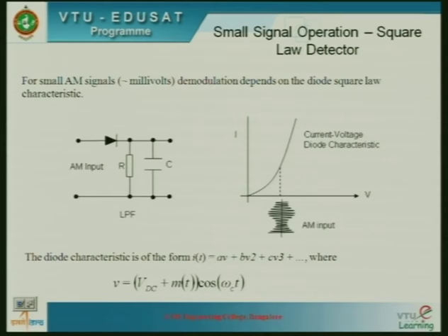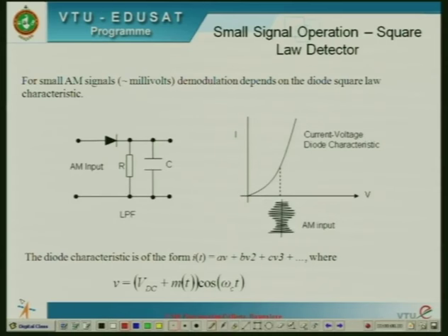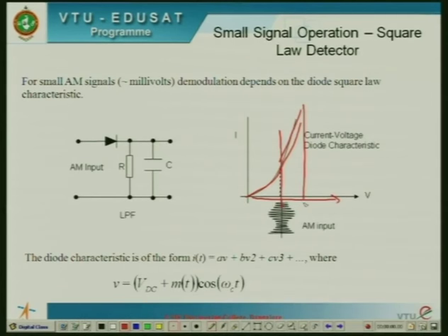So if we increase the voltage across the diode slowly, as we keep increasing the voltage, we find that the current also increases across the diode. This is the graph we get. If you look at the graph, there is a variation between voltage and current.